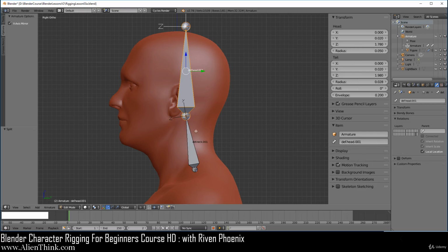Since all of these new bones are going to be non-deformed bones, meaning mechanical bones, we're going to click over here and type M.head.flex.C and enter. Now this is just a naming convention. It doesn't have a special meaning in Blender like the .L and the .R, okay?